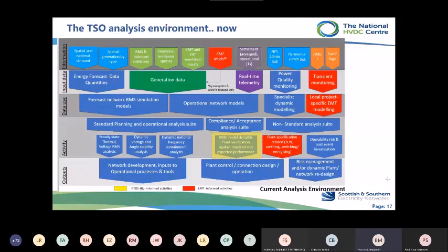We do use EMT analysis, to a certain extent, mainly in the factory acceptance environment, and RTDS, as a validation exercise, mainly to have comfort on our RMS behaviours and to ensure against some fairly broad standards that we are not exceeding any particular limit in relation to transient phenomena.